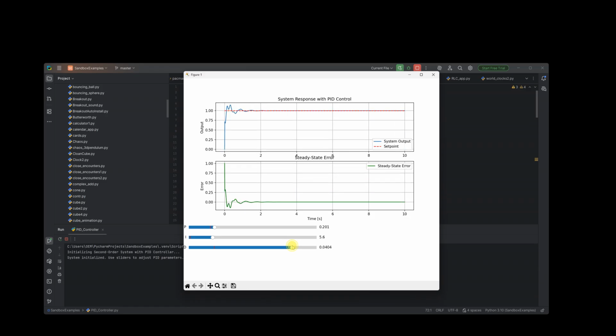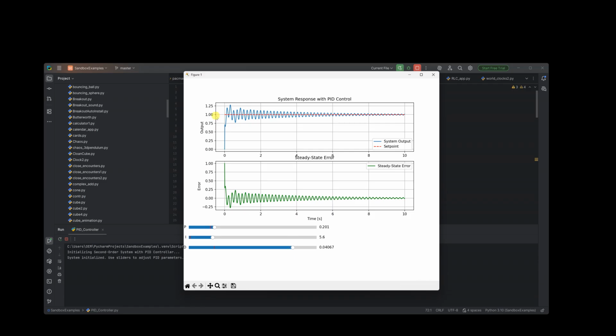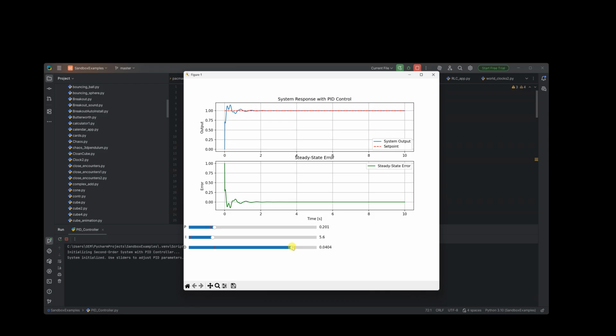So what you're seeing here is the structural resonance that's causing this, not the, if you like, the first Nyquist one. It's like it's got two crossings on the Bode plot. Again, you need to read my book to look at the details. You see that rather strange response. So that means I shouldn't be operating in that bandwidth because I've hit the structural resonance and it's starting to ring all over the place. So that's not the normal instability.